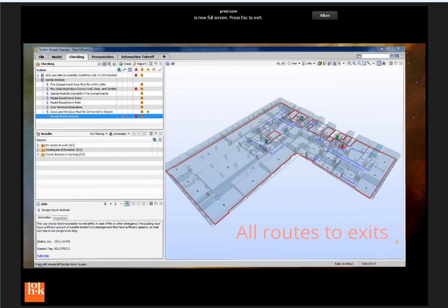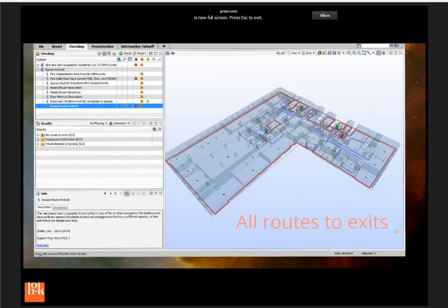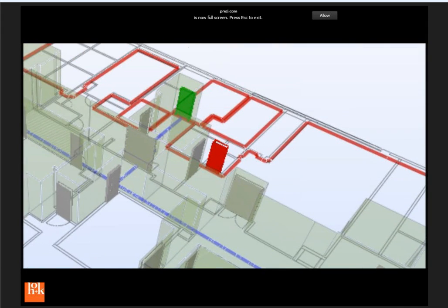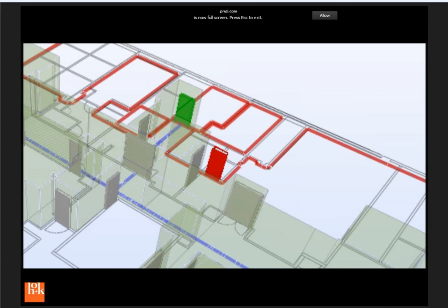So what it does then is it looks for all exits; it knows where its exit stairs are. It looks for the maximum distance between all those exits. In this case, our model shop room, this is all before it was actually built, was actually a little bit too far from the closest stair. I think the max path is 50. This was probably about 51 in some.